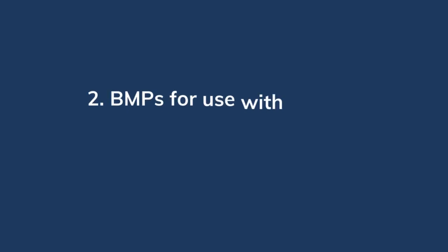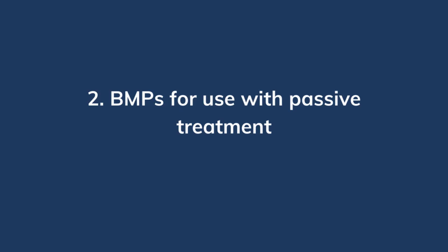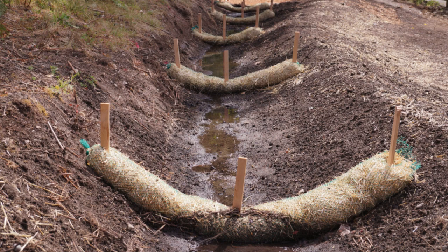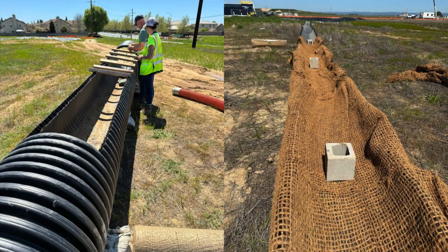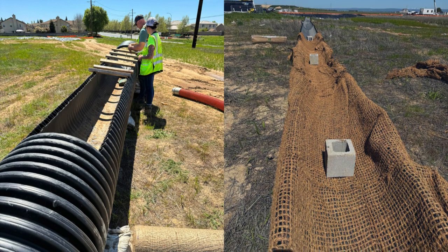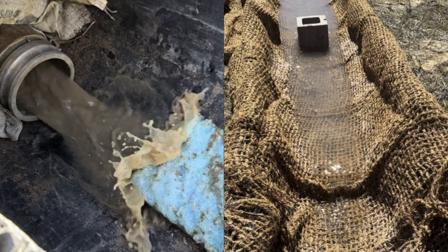In the treatment area, flocculants are introduced. Here, chemical reactions occur as the flocculants dissolve and bind with fine suspended sediment, forming heavier flocks that can settle or be filtered out downstream. The effectiveness of this process depends heavily on adequate mixing and reaction time.